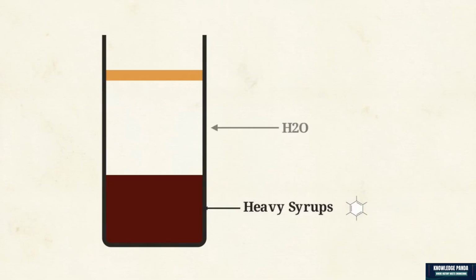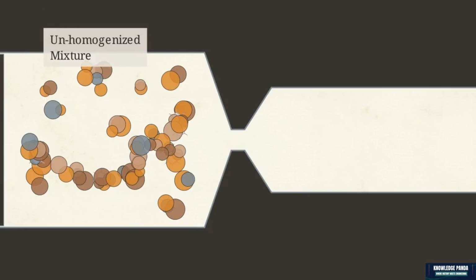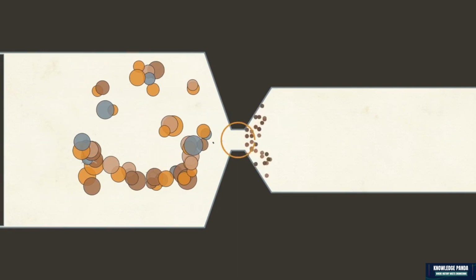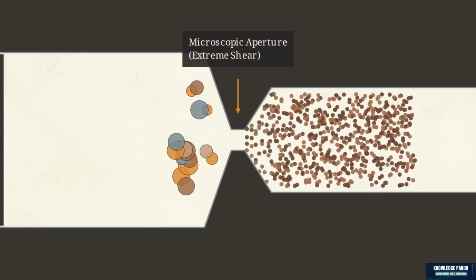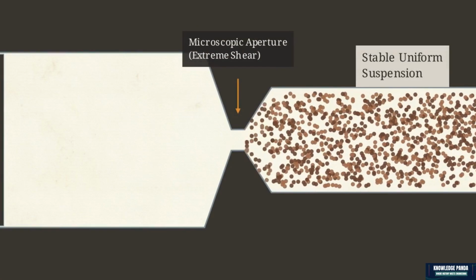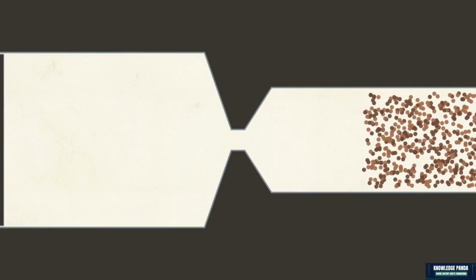Even completely sterile liquids carry the inherent physical risk of stratification. Over time, active ingredients in syrups possess varying molecular weights, meaning they will naturally separate out of the liquid suspension and settle into distinct layers. The fluid mechanics solution to this separation problem is industrial homogenization. Extreme mechanical pressure forces the formulated liquid through microscopic apertures. This violence breaks the large, clustered particles down into identical, uniform microparticles that will never separate.